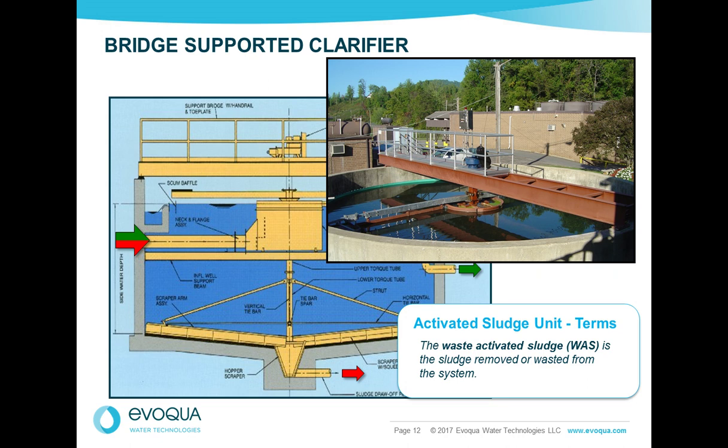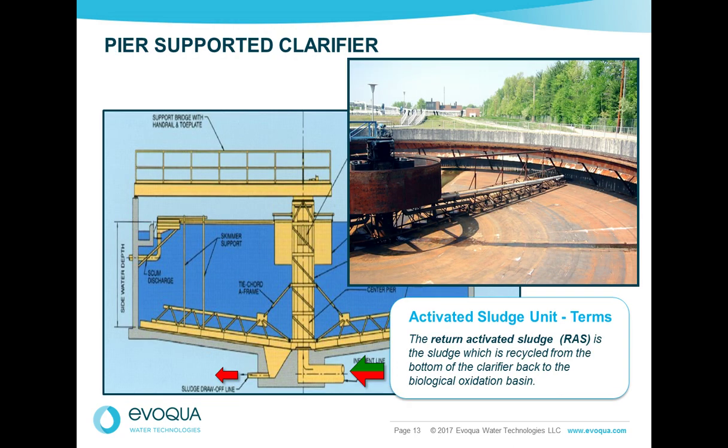There are many designs, as I mentioned. This is an example of a bridge-supported clarifier with a feed in through the side of the basin and into the center well. Shown here is another type of design, a pier support with feed entering from below grade.